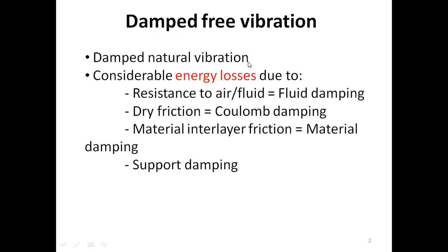The other type of damping is known as Coulomb damping. And this Coulomb damping is because of dry friction. When there are two moving parts that move relative to each other, which normally happens in some vibratory systems, two surfaces are moving relative to each other. So there exists friction, and because of that dry friction heat is generated, which is energy.